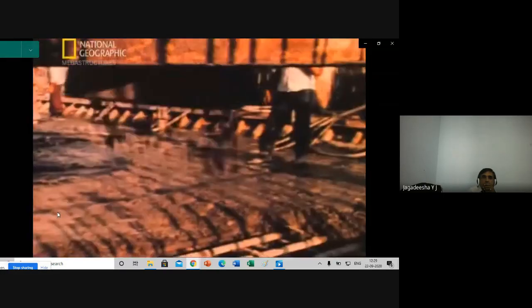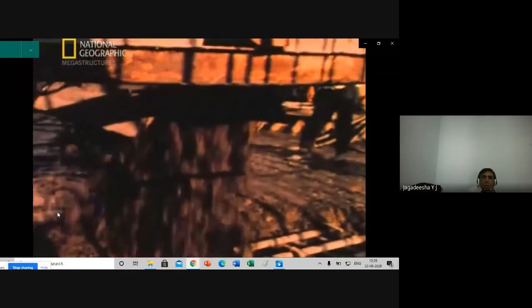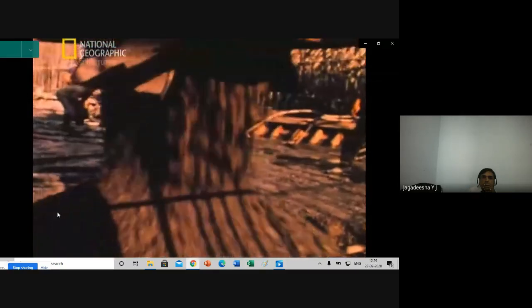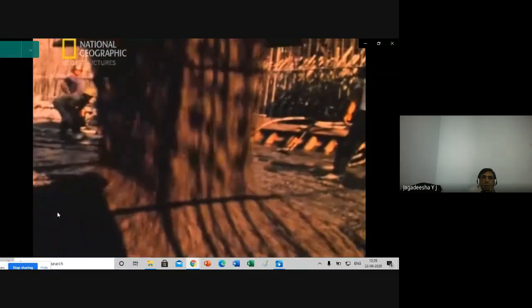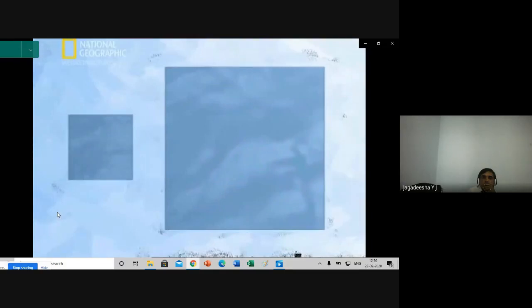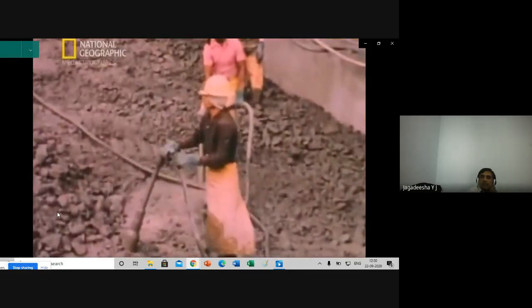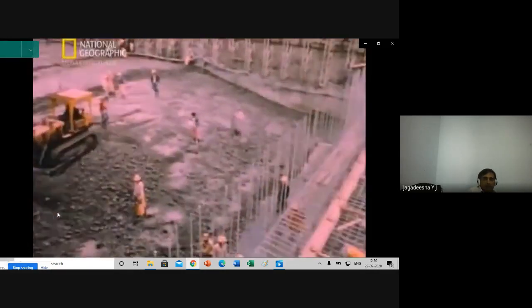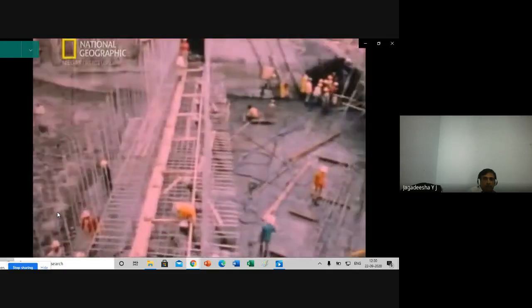But it wasn't just the scale of the job that posed a challenge for the engineers. If they poured this amount of concrete the usual way, it just wouldn't set properly. When concrete sets, the cement reacts with water, creating heat. In smaller concrete blocks, the core temperature cools and sets relatively quickly. But in large blocks, the core temperature stays high longer. And as the surface cools and sets at a faster rate than the core, hundreds of cracks can appear, fatally weakening the concrete.